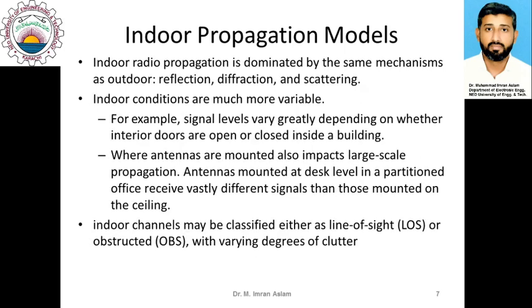So first important thing is that the indoor propagation is also dependent on the same phenomena as we discussed for outdoor propagation. Primarily the electromagnetic phenomena that govern the indoor propagation are reflection, diffraction and scattering. So all these phenomena are also available in indoor, but the problem is indoor environment is more cluttered, and there are a variety of different stuff, and the deployment can be in different scenarios. So signal depends on the layout of the buildings and interiors.